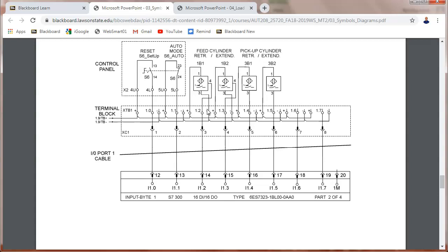Well, it's a 3-wire sensor. So if it comes out of 4, this is going to be black, an open output. White would come out as number 2.